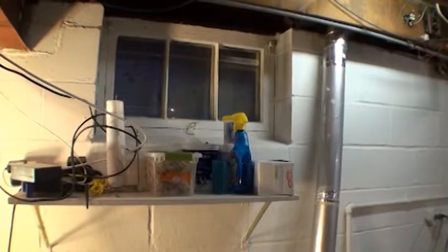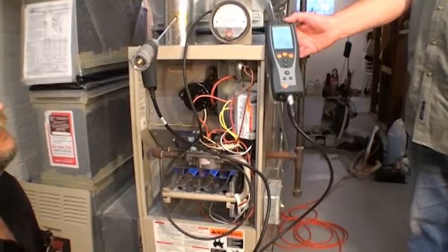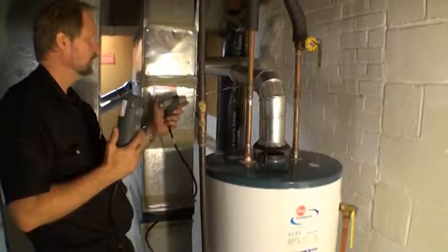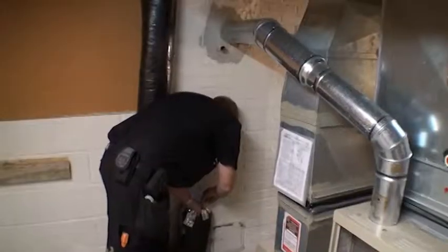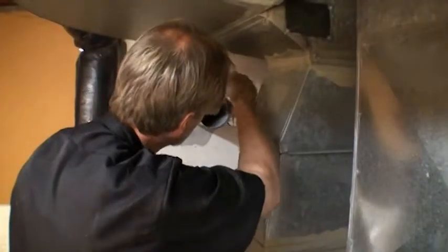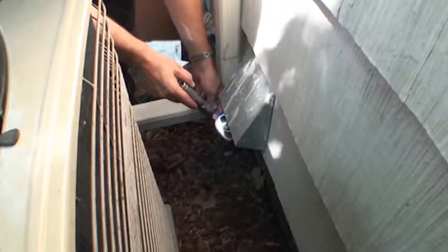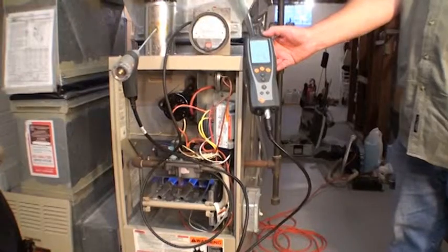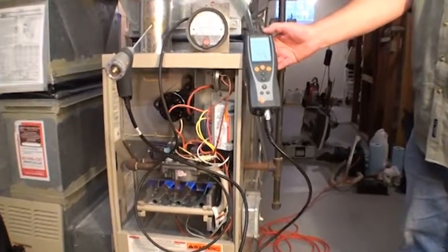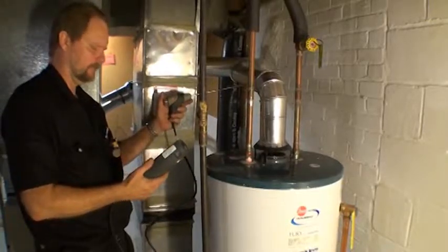If any appliance does not pass the test, try opening a nearby window or door to the exterior. Retest the appliance, and if the appliance now meets the pressure measurements, then consider installing combustion air. If the appliance still does not meet performance indicators, look for and correct other problems, such as chimney or venting blockages. Retest the appliance after corrective measures have been completed. If the appliance still cannot pass worst-case draft, call Community Action.